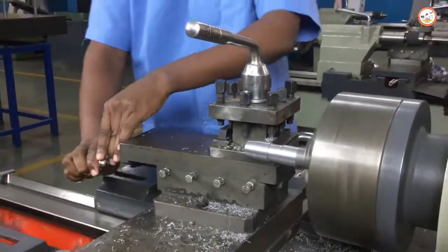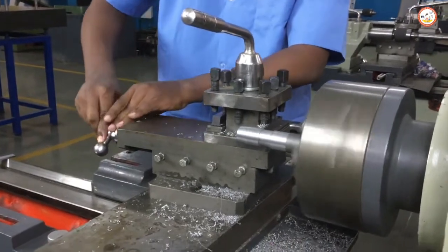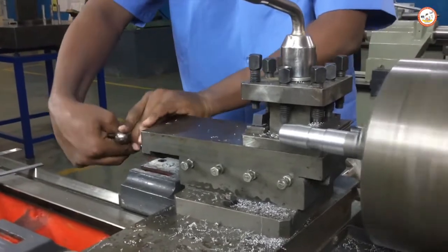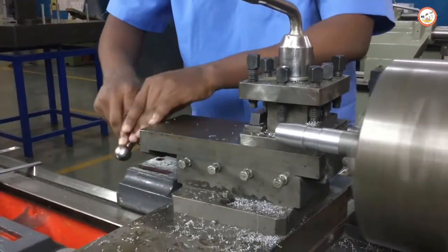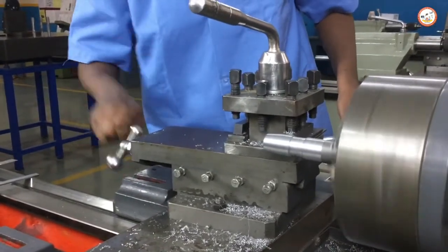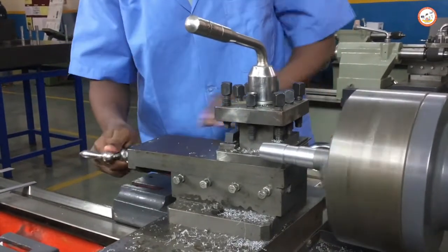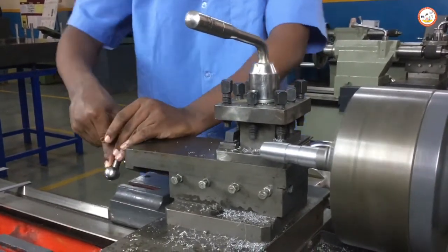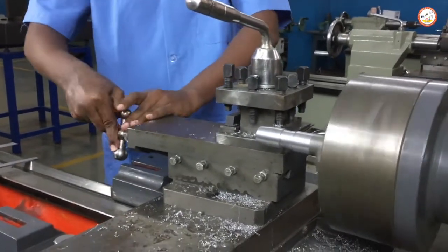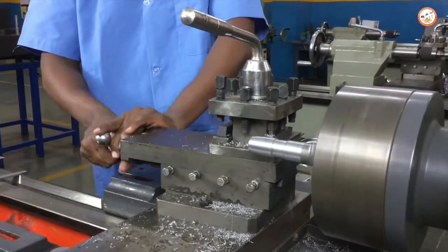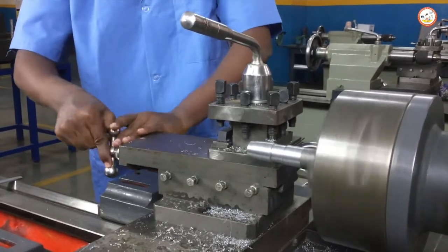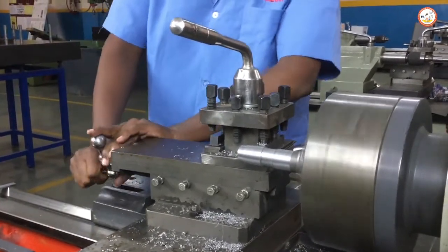The depth of cut has to be given slowly so that a good surface finish is obtained during the taper turning operation. And constant movement of the compound rest hand wheel is very important. Once the required degree of taper and diameter is achieved, the tool is moving at an angle of 4 degrees. As we have said, care should be taken not to rotate the carriage hand wheel.